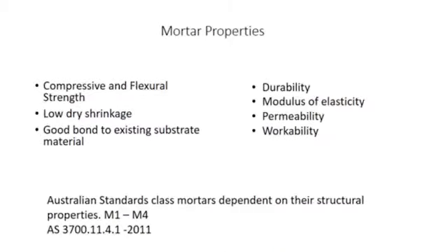The design of the mortar's properties largely relies on the existing concrete. In most repair applications, the mortar is needed to perform monolithically with the existing concrete structure. When there is a significant difference in the properties of the new material and existing substrate, forces can focus and exert mainly on the bonding plane, causing separation and an accelerated deterioration of the repair.